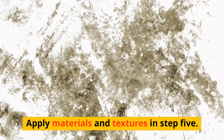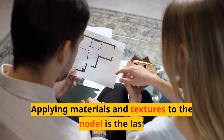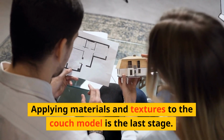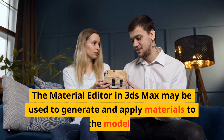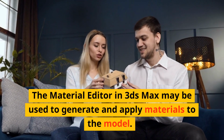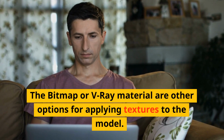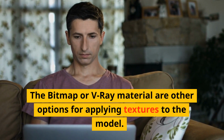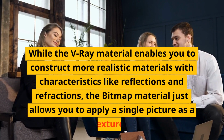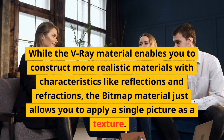Apply materials and textures in Step 5. Applying materials and textures to the couch model is the last stage. The material editor in 3ds Max may be used to generate and apply materials to the model. The bitmap or V-Ray material are other options for applying textures to the model. While the V-Ray material enables you to construct more realistic materials with characteristics like reflections and refractions, the bitmap material just allows you to apply a single picture as a texture.